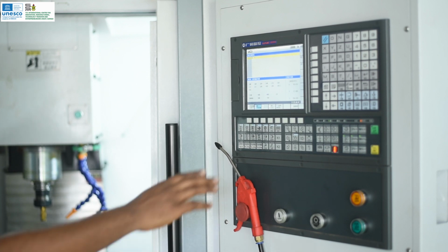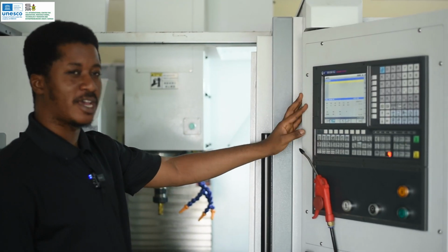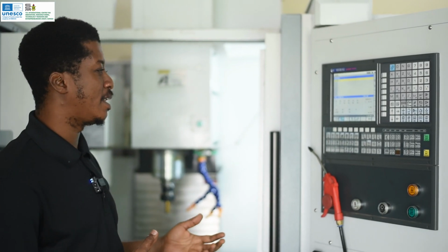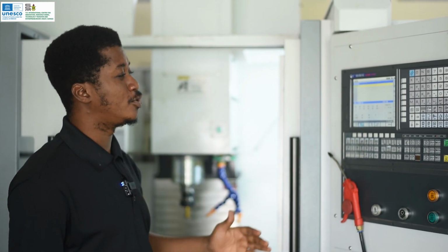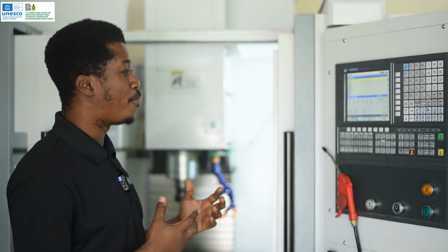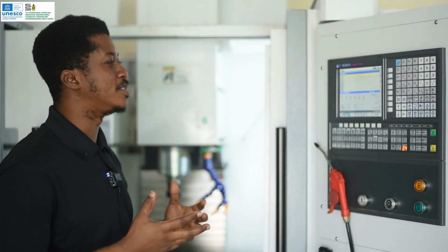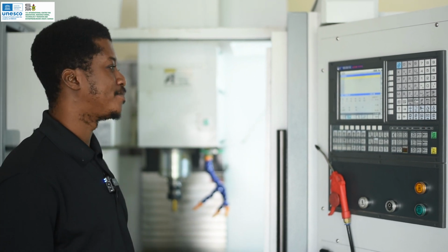As you can see, we are now in T4. Tool changes are usually handled inside of your CAM program and are done automatically once your program is running. But MDI mode allows you to quickly test various programs that you're not sure about, or sections of your code that don't seem to run, so that you can troubleshoot them.